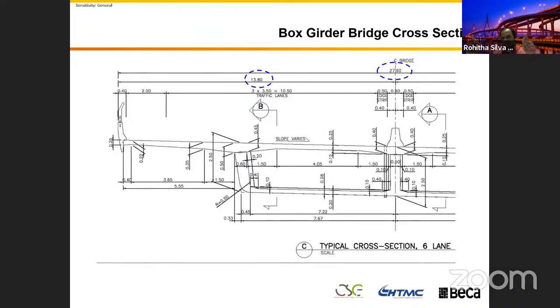The span of the slab is 1.8 meters going against 27.6 meters. It's got about a 6 meter cantilever, and then you have 2 beams in between. It's more than 7 meters. Yeah, you can go to these extreme ends because when you put this loading, all this will bend and behave. We're going to learn this later.